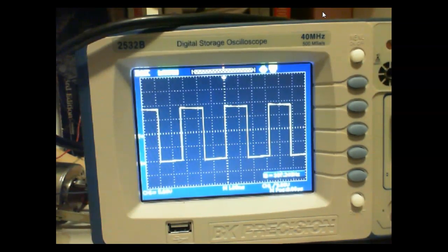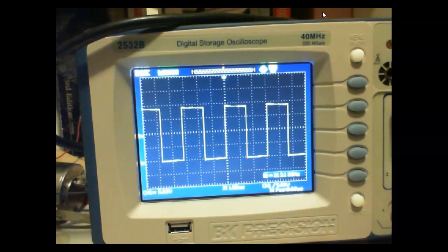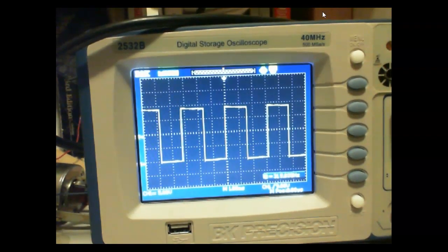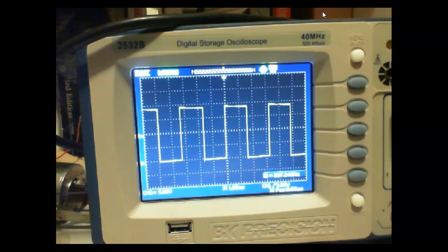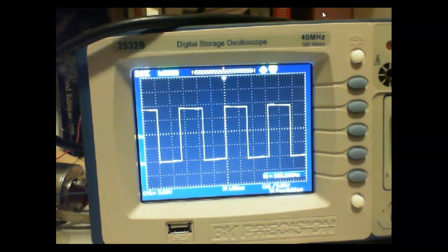So it's one over our time, which in this case would be 3 milliseconds. So it's 3 milliseconds times 2,100. Then we take the reciprocal of that, and then we multiply that by 60. Because our scope measures time in seconds, our rate would be revolutions per second. So what we got?